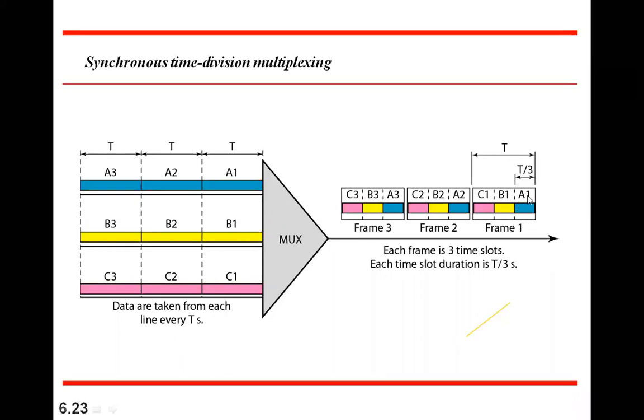So in that, he is getting only 1/3 of the part. Within that, his data is sent. The remaining two parts are shared by the others, and again the next frame starts. Again in the next frame he gets 1/3, and again in the third frame he gets 1/3. Like that, everybody is getting turns, his slot, to transmit his data.